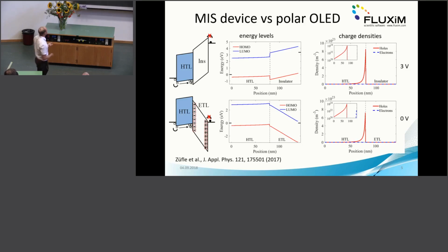So we did some drift-diffusion simulation. It turns out that it really behaves the same way. These were the schematics, and these are the simulated band diagrams, and they really look like we assumed. Especially if we look at the charge densities, we find that the holes really accumulate at this internal interface. This means that the analytical model for the MIS-CELIV experiment can be employed.